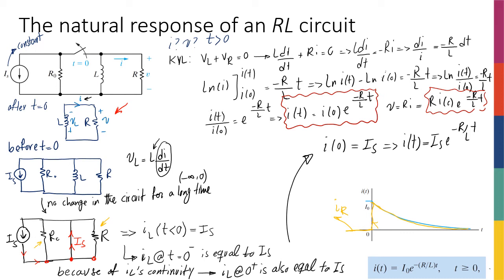Well, that's kind of true if it was only resistors, right? But one thing that we know about inductors and capacitors is that they can actually store energy for a limited amount of time, and that is why we have a transient behavior. You see that it becomes zero after a while, right? So it's not like if you leave a resistor and an inductor connected on the table, they're not going to have any current or voltage after a long time.